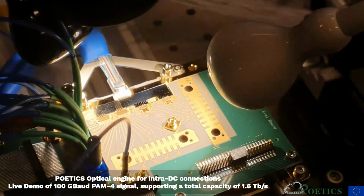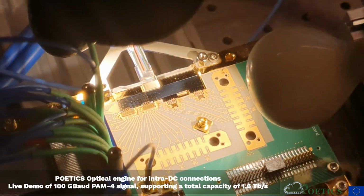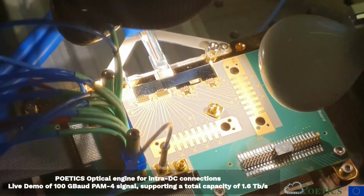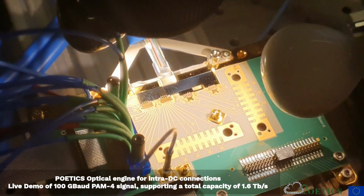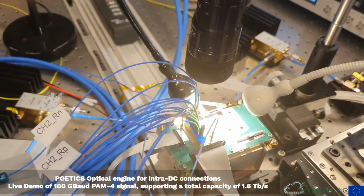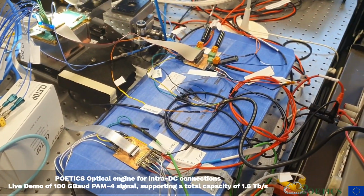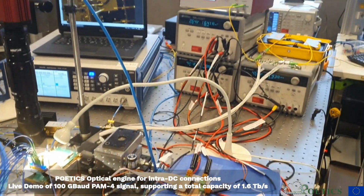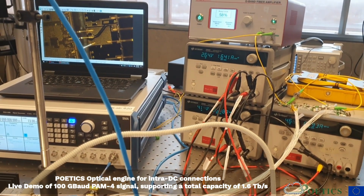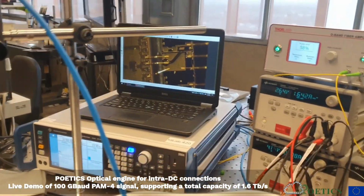On this board that was designed by Fix, we assembled the transmitter chips, the receiver chips, the photonic chips, and the PolyBoard. It then connects to the fiber array. On this board, you then see a fan out going to all our power supplies. The power supplies provide biasing for the optical elements, provide the different supply voltages that we need to make the chip work. And then we also see the digital interface that we use to program the chip.